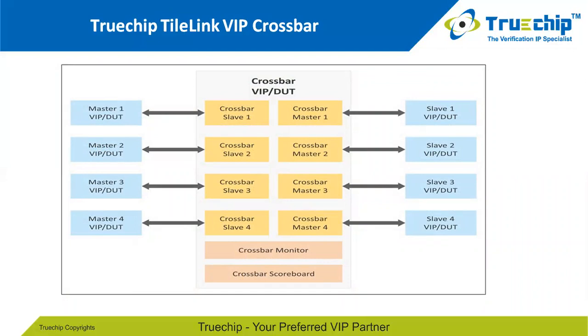The crossbar can also be replaced with the DUT, in which case a crossbar monitor and the scoreboard can be plugged in as a crossbar checker. All the masters, the slaves and the crossbar can be replaced with the DUT, and the complete VIP will work as a passive monitor. As per the requirement of multiple crossbars in a system, multiple environment instances are also possible.